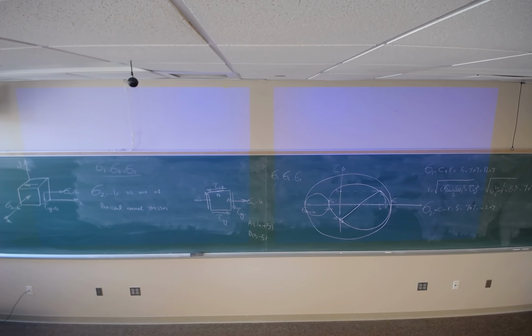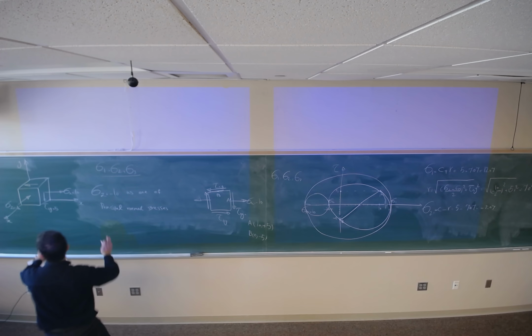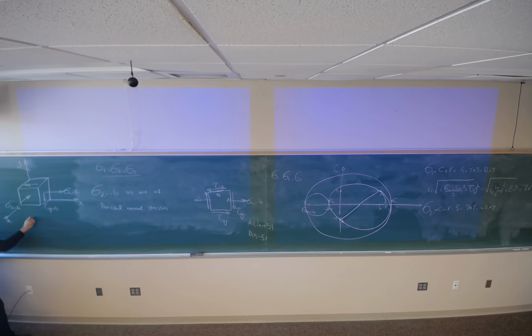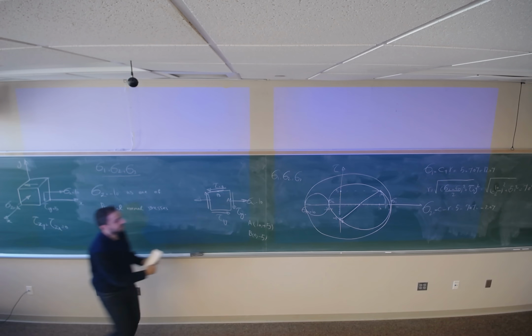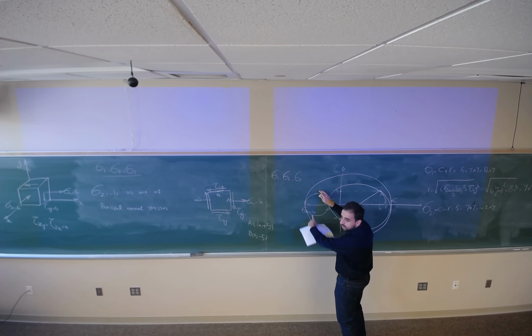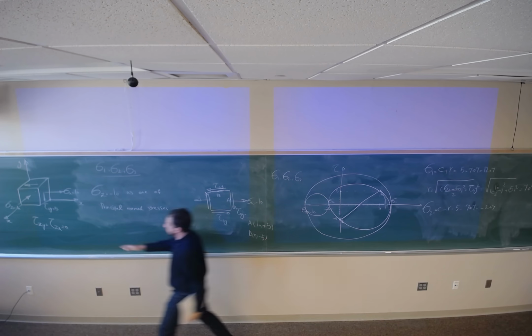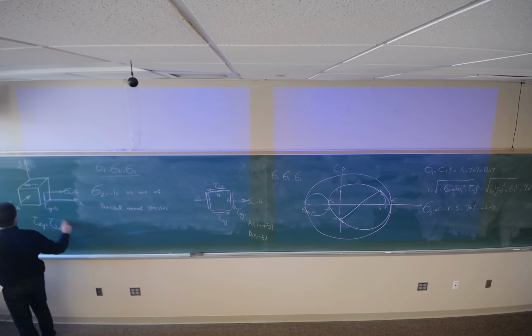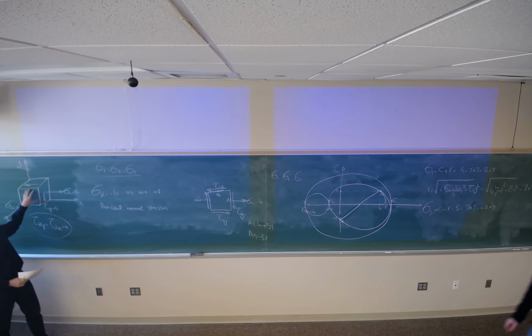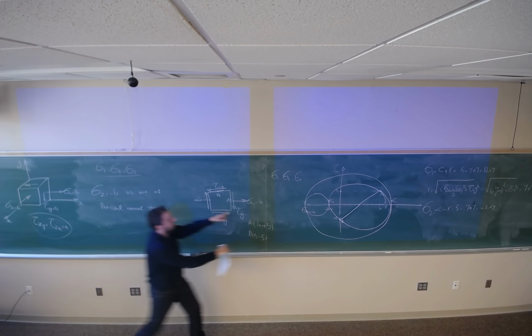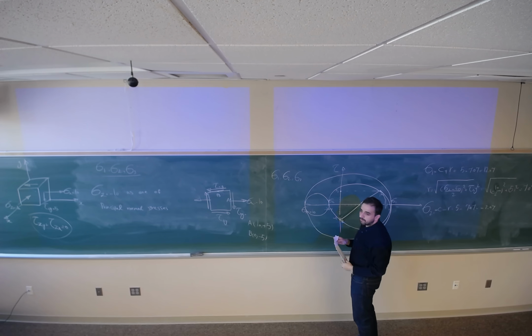Because it's coming from here. Tau zy and tau zx are equal to 0. If they had any terms, then I had to work on this circle to find those points. But since these two are equal to 0, this plane doesn't have any shear stress. For that reason, I'm just working with these 2 points. Okay, thank you. Yep.